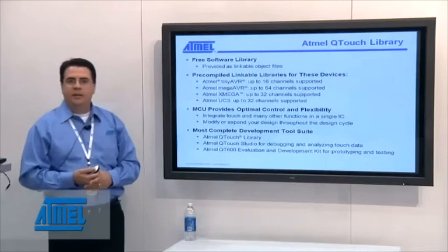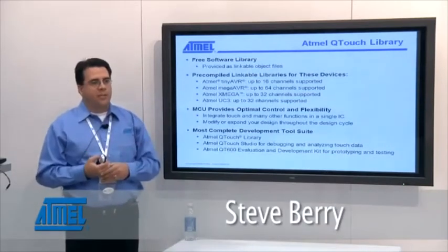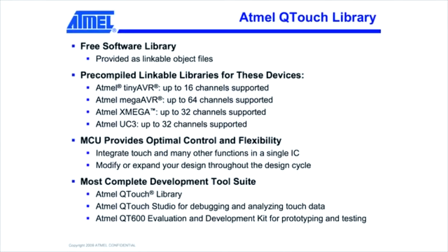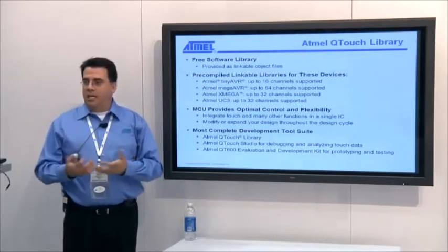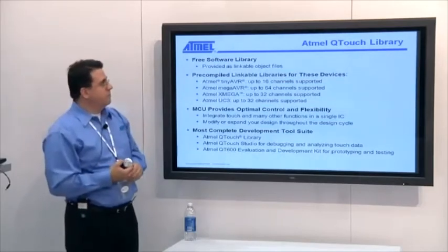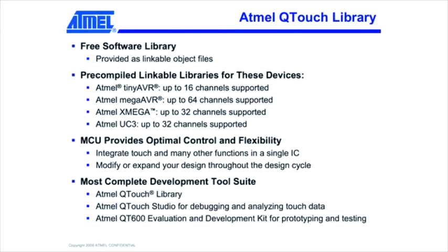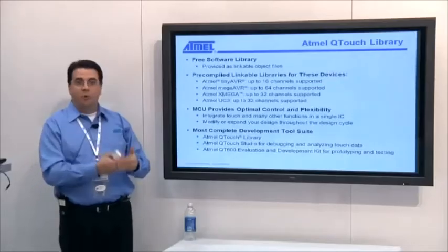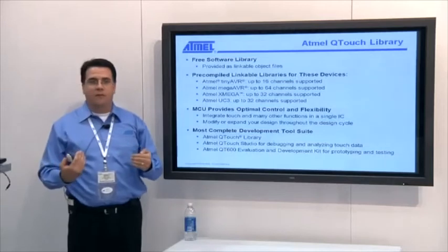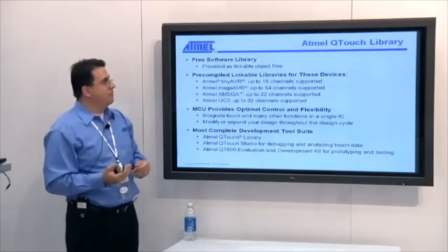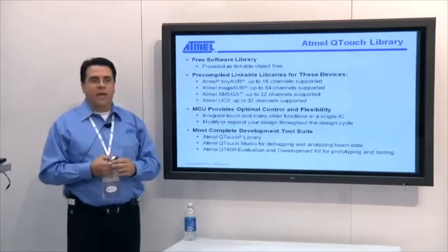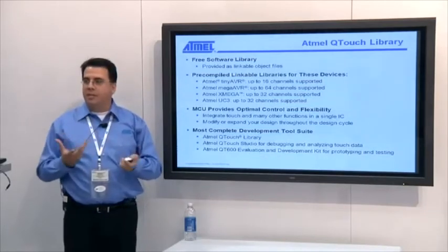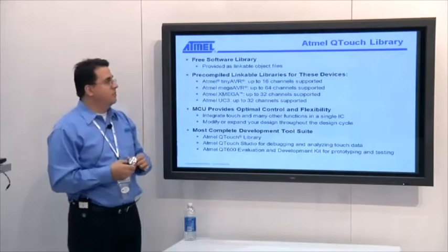So, the QTouch library. Probably the greatest flexibility, the greatest overall capability that we offer in our solution portfolio is through the QTouch library. The idea is to support touch in any of Atmel's microcontrollers, and we want to provide this capability free. Today we have a library which supports most of our 8-bit and 32-bit AVR devices, downloadable from our website for free. It's a precompiled and linkable library so that the user does not have to worry about any of the implementation details of the touch interface.